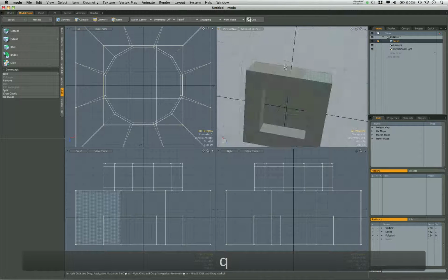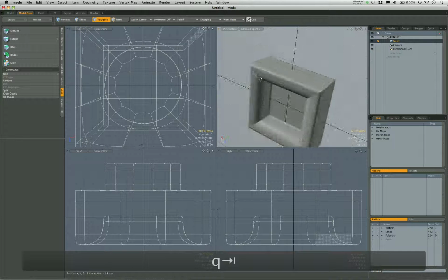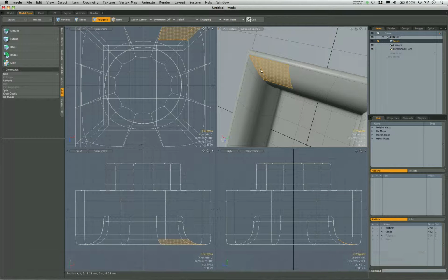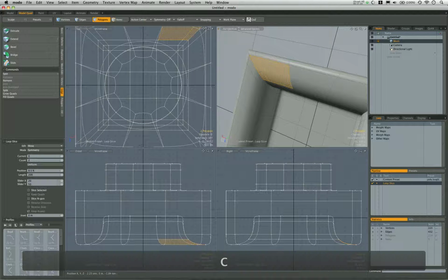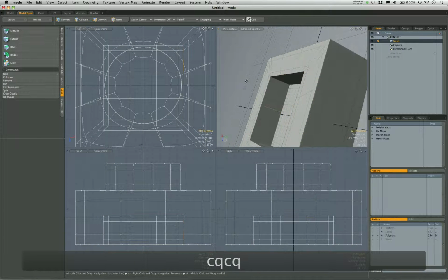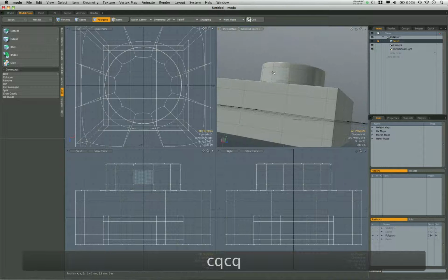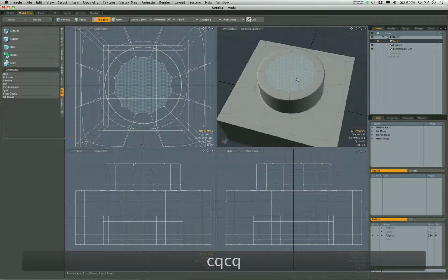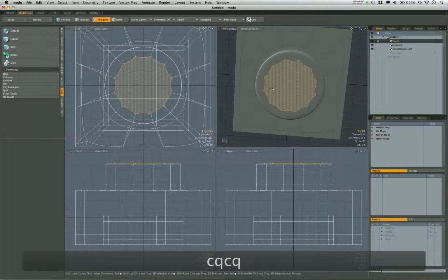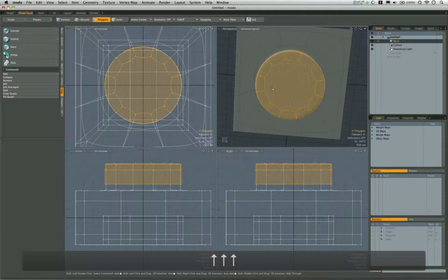All right, so now if we go back to subdivision surfaces, we'll see we do have sharp corners, but we have roundy edges this direction. So we're going to, again, add in some paired loop slices here and here. And that will sharpen that up. And now all we have left to insert is the little insert that is underneath. Now, that insert happens to be 2.4 millimeters in height, which is half of what this one is.